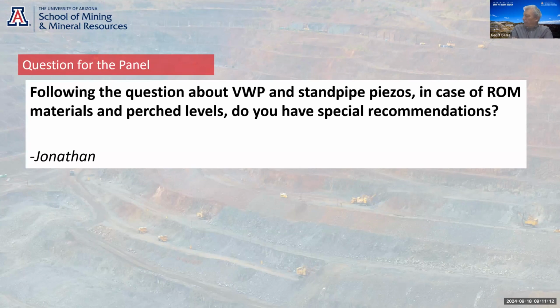Jeremy, you want to have a go at that? Oh, yeah. So I think the problem with raw materials is loss into the leach pile or into the dump, and so thicker grout, possibly some lost circulation material, possibly condition the hole with lost circulation material before you put in your piezometer installation. Use fine slotted casing to minimize grout loss, and put in multi-level standpipes if none of those work. But we're doing some experiments on that right now for Freeport McMoRan here at Morenci.